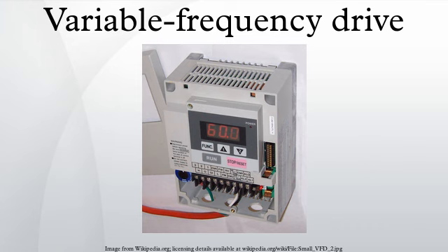However, when the proportion of VFD and other non-linear load compared to total load, or of non-linear load compared to the stiffness at the AC power supply, or both, is relatively large enough, the load can have a negative impact on the AC power waveform available to other power company customers in the same grid.